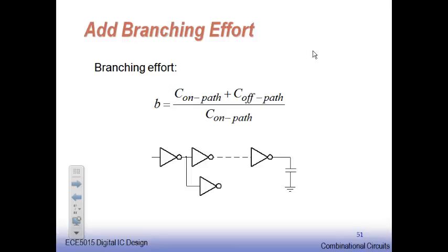Now, so far we were talking about what? Its inverter and its own inherent delay, intrinsic delay we had discussed, and sizing PMOS, NMOS we discussed. Then what did we have? Get this inverter made bigger for a more complex gate. And when I go for a complex gate, instead of one P and one N device, you are going to be having more number of P devices and more number of N devices, equal numbers. And based on that, I said you will have its own internal delay formed. And we also discussed about the fan outs.